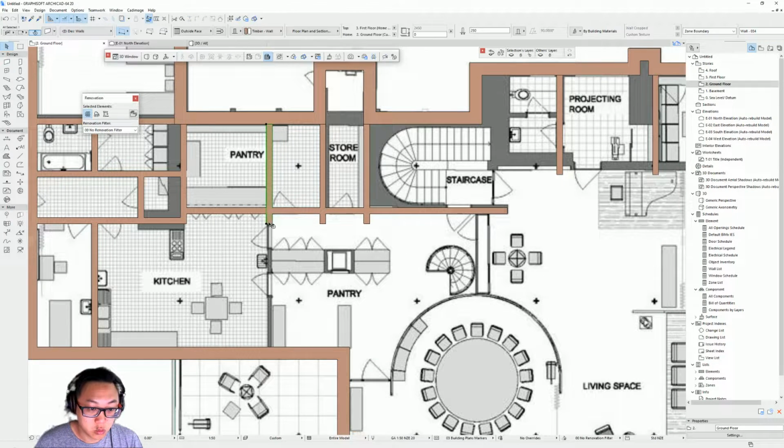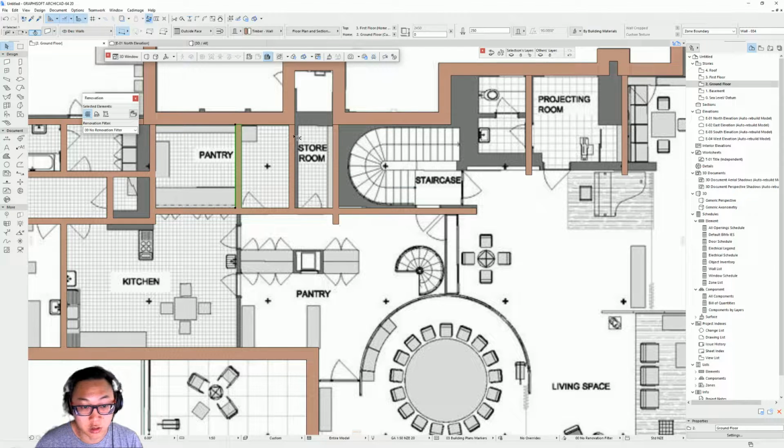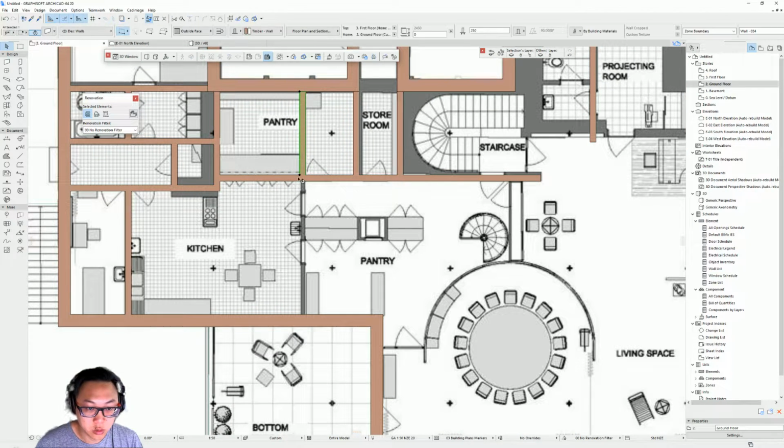And select the wall tool, press Ctrl to get the scissors. And you can see you can use the scissors even on walls that you haven't selected. And actually this wall needs to go all the way down, and this needs to be cut. And actually this wall doesn't go all the way to the top, so I can just select the point and drag it down. If you press Shift, it will stick it to that axis. I'm just gonna line it up with this corner.